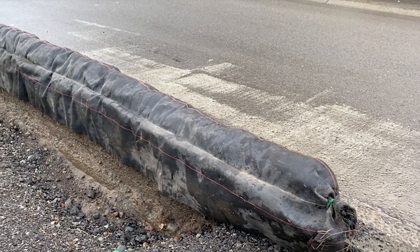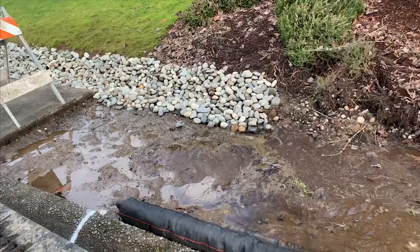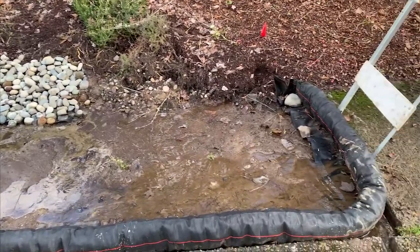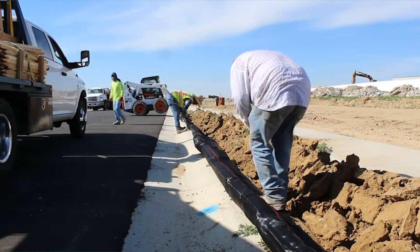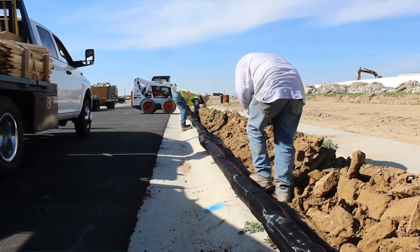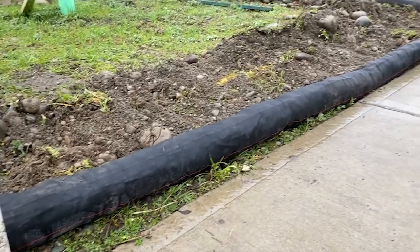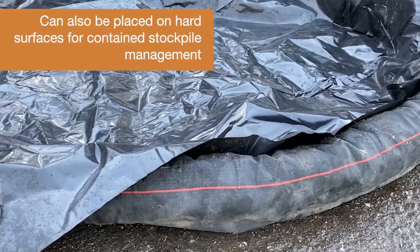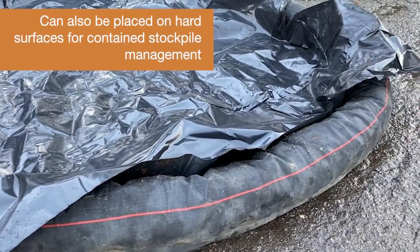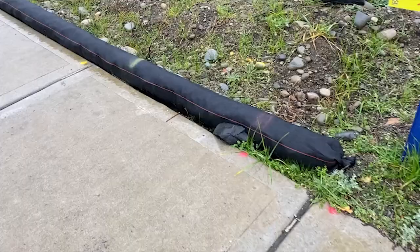That way you're going to retain the integrity of the wattle longer, but should not be done on steeper projects. There are also a lot of synthetic or reusable wattles that are out there, and these wattles oftentimes have a flap associated to them, very similar to silt fence. You've got an extra fabric flap that gets buried into the ground, and that allows the entire profile of the product to stay above the ground so that you're not losing that 2 to 3 inches of freeboard like you would on a straw wattle by burying it in the ground.